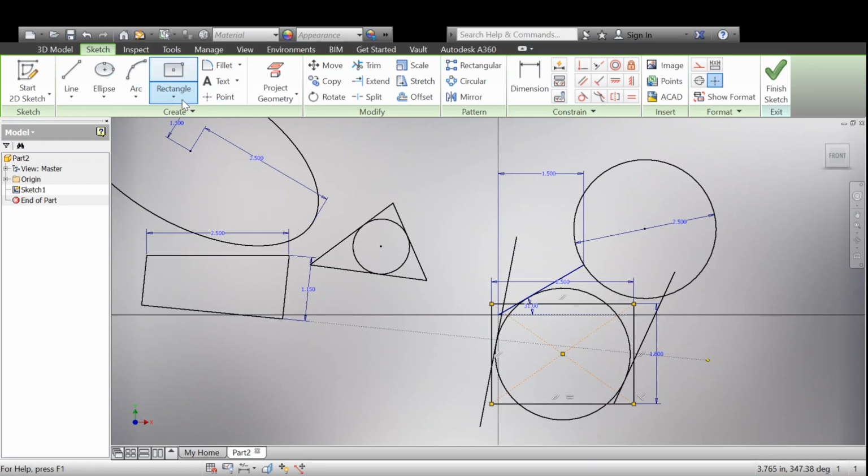At times you're going to want to create a point in space, and that's right here. It literally creates a point. By clicking on point, it allows the cursor to place a point anywhere you'd like. Look at all the points I'm clicking on now. They're all appearing as crosshairs on the screen. Why might I want these points? It's possible that I want to have some sort of dimension with respect to that. So let me show you. Now when I choose dimension, look at all these points I created. See all these little crosshairs on my screen? Those are all points. It's very possible that I want an object to be a certain distance from that point.